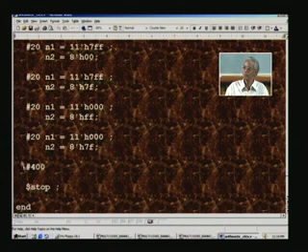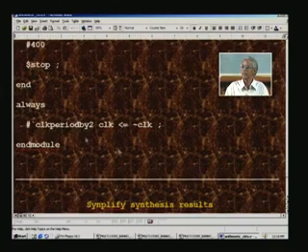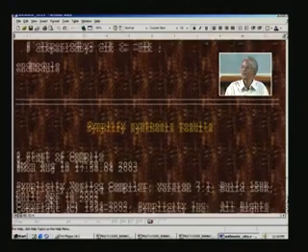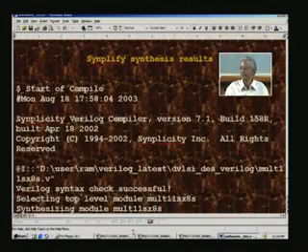So, we give some more cushioning for processing further, say by 400 nanoseconds. This may not be required really, it can be even 100 or even less, and finally stop. This completes the test bench with a final always statement, wherein you toggle the clock as usual, and that is the end module here. We have simplified results, and before we go into these results, we will look at the waveform here.